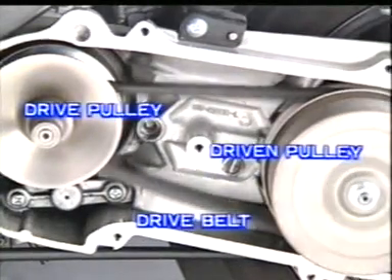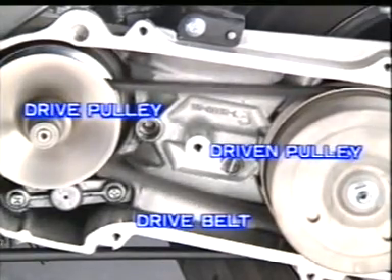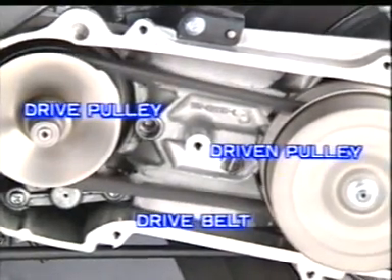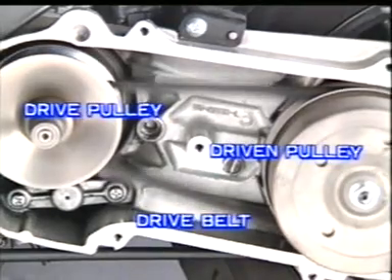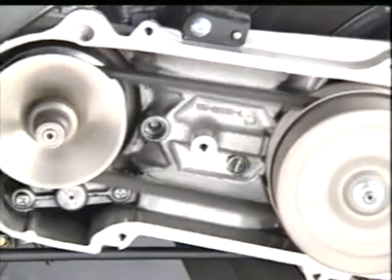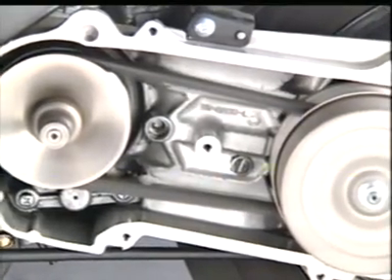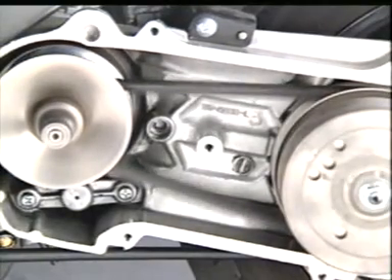The drive pulley is attached directly to the crankshaft and changes the width of the pulley in response to conditions such as throttle operation. This changes the position of the drive belt, which automatically changes the reduction ratio. This system allows smooth increases and decreases in the motorcycle speed and drive force.